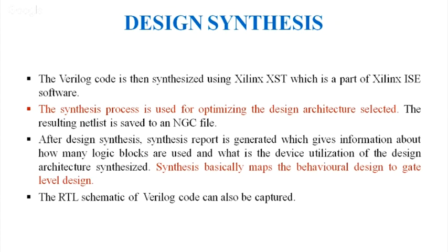There are multiple logic blocks available in FPGA, so how many blocks are used in our design, and what is the device utilization of the design architecture. Basically, synthesis maps the behavioral design to a gate level design. So our behavioral design, what we have written in code, is converted into a gate level design. We can capture the RTL schematic of the Verilog code which we have written in Xilinx ISE.